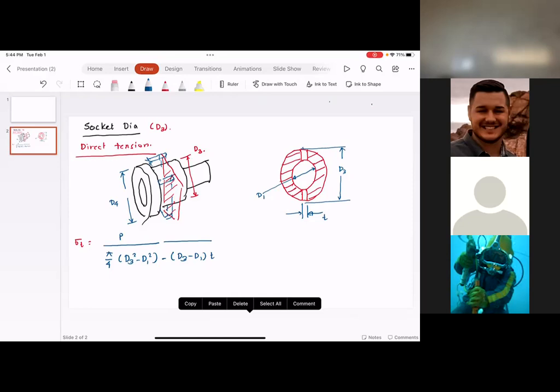The design procedure is exactly the same. You design half of the joint and then just duplicate it onto the other side. There's an example in the textbook where the double quarter joint is used. So there could be variations of the quarter joint. And we will look at the knuckle joint, wherein instead of a quarter we have a pin, and we would perform a similar type of analysis. At the end, all these mathematical tools, these basic mechanics of materials principles, will give you confidence to design using the solid modeling software.